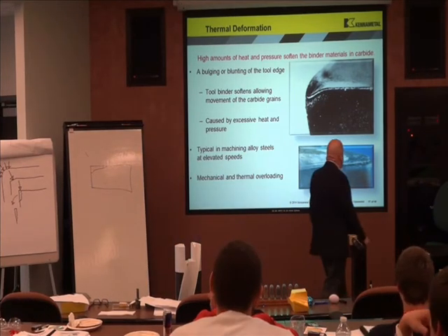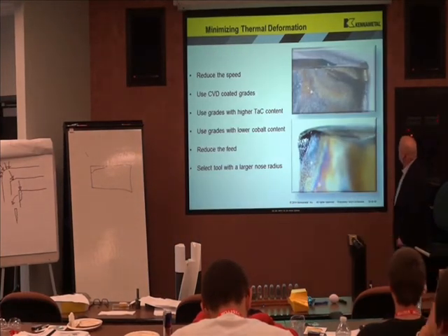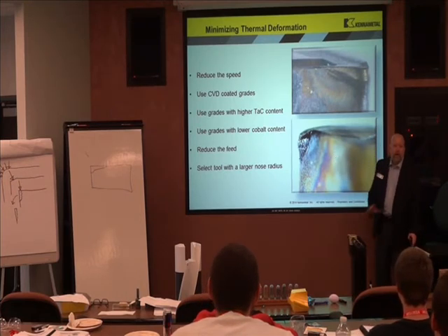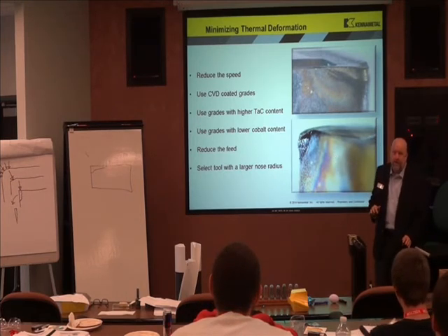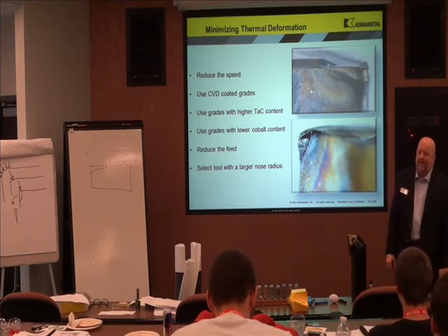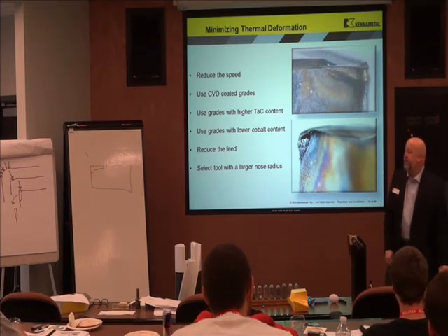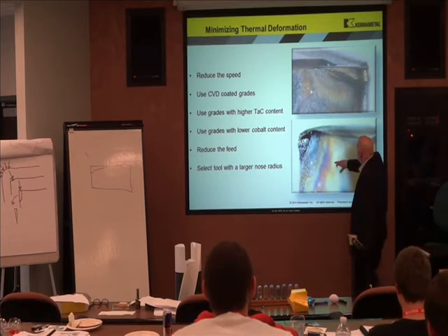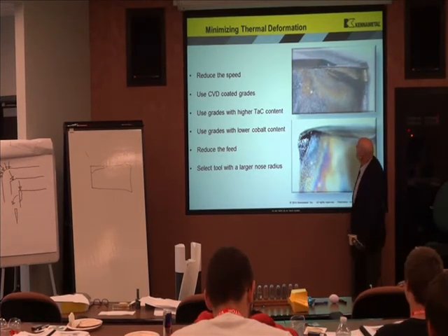This is just by too much heat and pressure. So the only thing you can do is... rainbows are pretty. If your cutting tools look like rainbows, you may be doing something wrong. Here's your sign. Rainbows aren't in cutting tools. You can get a nice little rainbow color around it. That's too much heat and pressure.